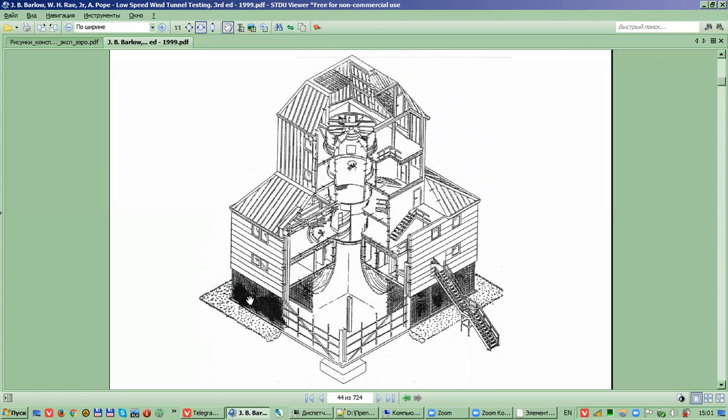This is the inlet. Here we have screens, a mesh of wire, and this mesh, like screens in a wind tunnel, breaks down turbulence vortices and gives high quality airflow at the inlet. This building has its first floor as the inlet for the wind tunnel. After the contraction section, the flow changes direction from horizontal to vertical and goes into the test section.